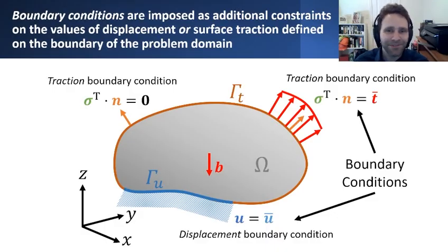And the components of traction that are exposed on a particular surface will depend on the orientation of the exterior portion of the boundary. And we can relate those prescribed components of traction, which I'll call T with an overbar, to the corresponding components of stress through a relation that involves the dot product between the particular surface normal n and the stress tensor itself.